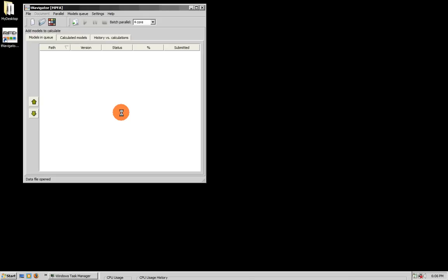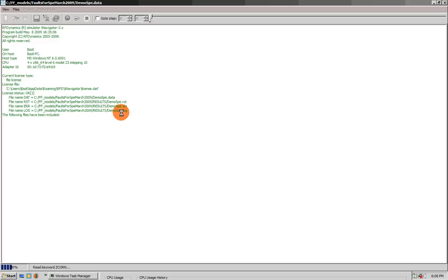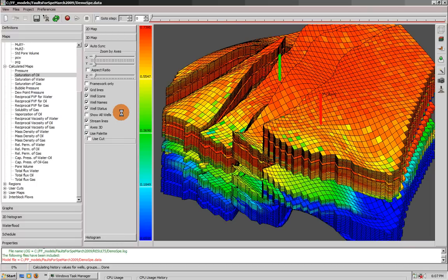This is a tNavigator training course. We show how to split the model into arbitrary fragments, how to take advantage of multiple interactive restarts of parallel calculations, and how to add well patterns and simulate hydraulic fractures using the new generation of adaptive multipoint flux approximation and full permeability tensor. This is the model loaded in Eclipse 100 format.